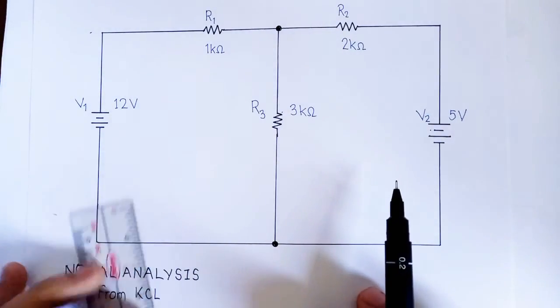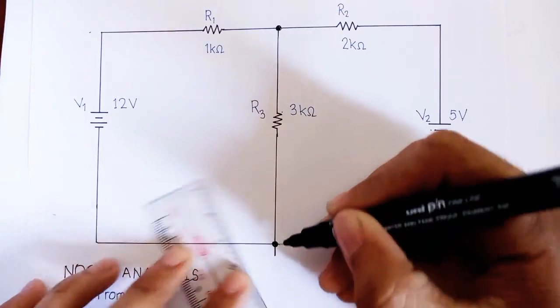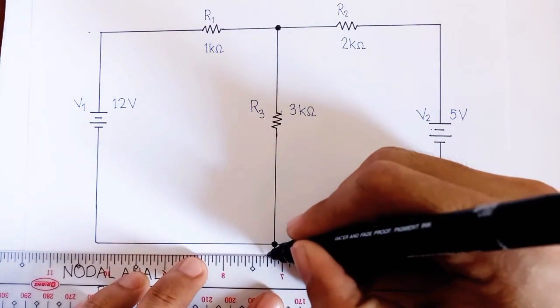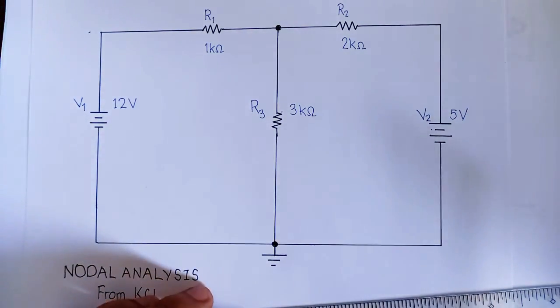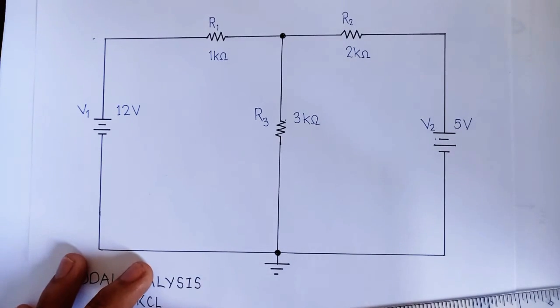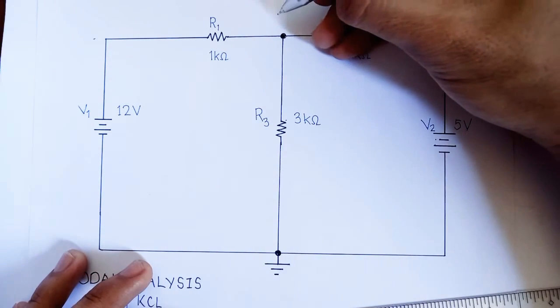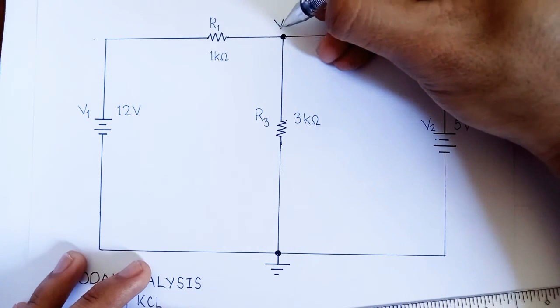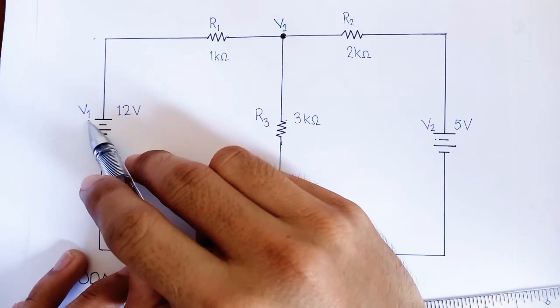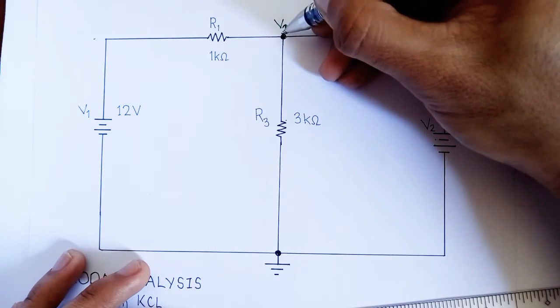Okay, sa nodal analysis, magkakaroon tayo ng isang reference node, gagawin nating ground. Ayan. So, gagawin natin siyang ground. Okay, and magsasolve tayo sa nodes. And yung mga natitirang node, papangalanan natin sila, okay? Itong node na to, since nag-iisa lang siya, tatawagin natin siyang node 1. Or, tawagin na lang natin siyang V1. Ay, sorry, ito pala V1. Sige, tawagin natin siyang V3. Alright, ganun lang kadali yun. V3.